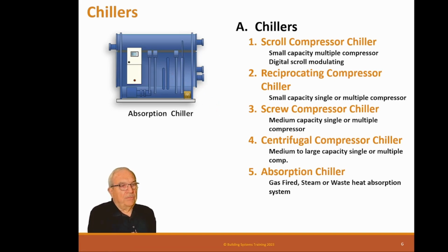They're a real pain to keep operating well, but they basically are gas-fired, steam-fired, or waste heat absorption systems. And what they do is they take heat from some source and put it in, and it actually heats an absorption material and runs it between two stages, and we have condenser water coming in to cool it, and it actually produces a cooling effect by the absorption of this material that's inside the chiller.